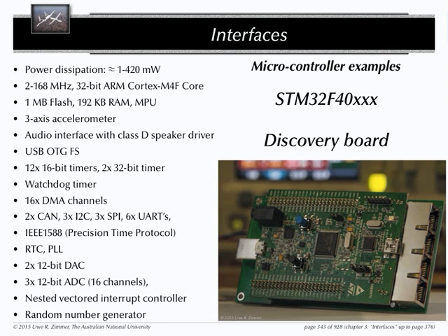If you go to 500 megahertz and beyond, this will be a bit more problematic. The PowerPC community is usually going a bit further. Here you have the embedded PowerPCs. They're clocking a bit further because their power consumption has a very low starting point to start with. They have a good possibility to crank that up further. And the embedded PowerPC devices you often see in routers, in network devices, where you actually need the clock rate to keep the performance pumping here.